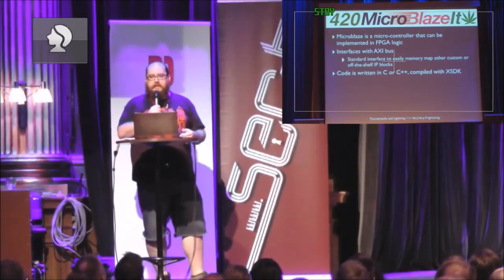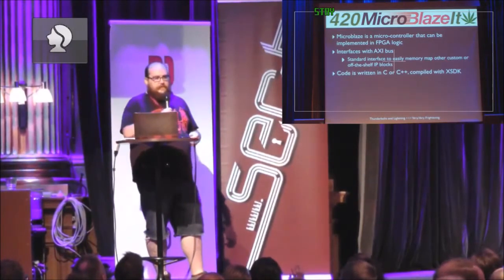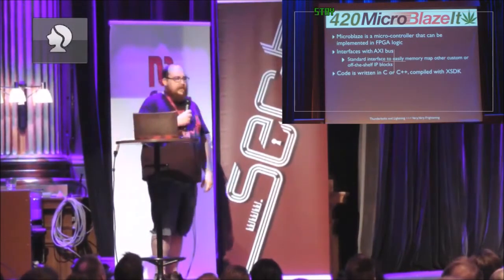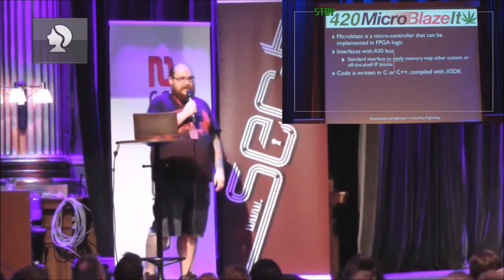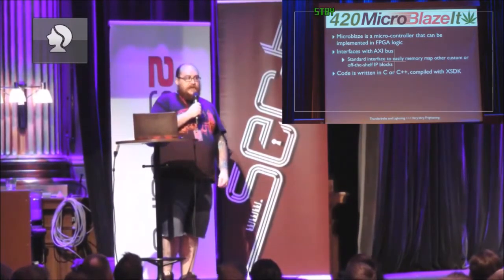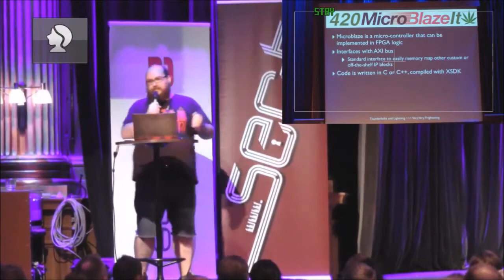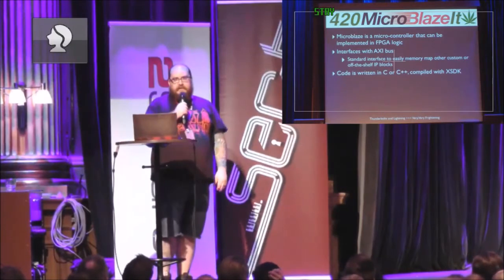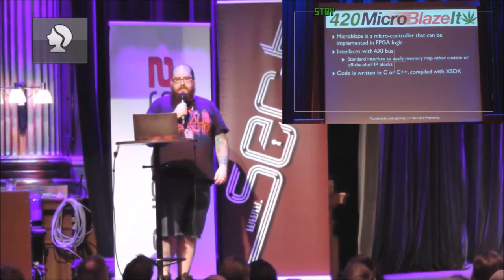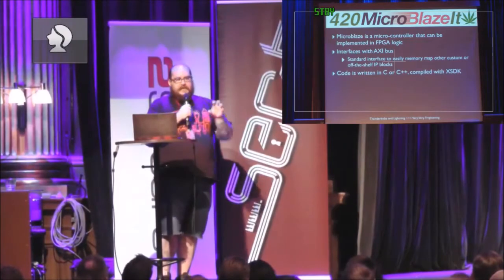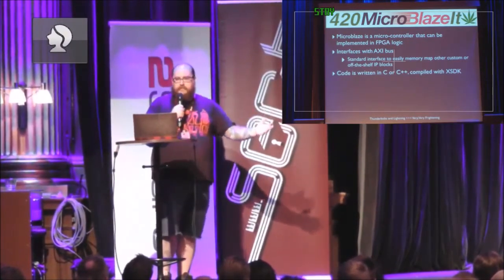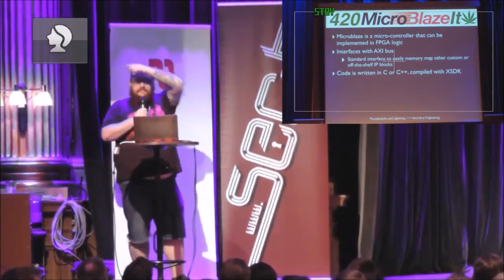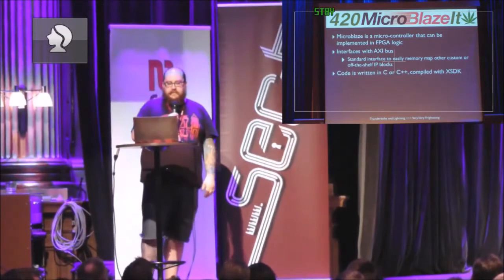How many people have done any FPGA development here? Okay, so a few. So for everyone else, don't. It's hard and it's really annoying, right? Unless you're an engineer. From a software guy's perspective, it's a real pain in the ass. And debugging stuff is really difficult. I shouldn't say don't. It's heaps of fun as well, but it's frustrating. So debugging issues with your logic, you inject a logic analyzer core, and then you talk to it with this ChipScope logic analyzer program or whatever platform you're using, and you just get lines out of it, which makes debugging tricky.